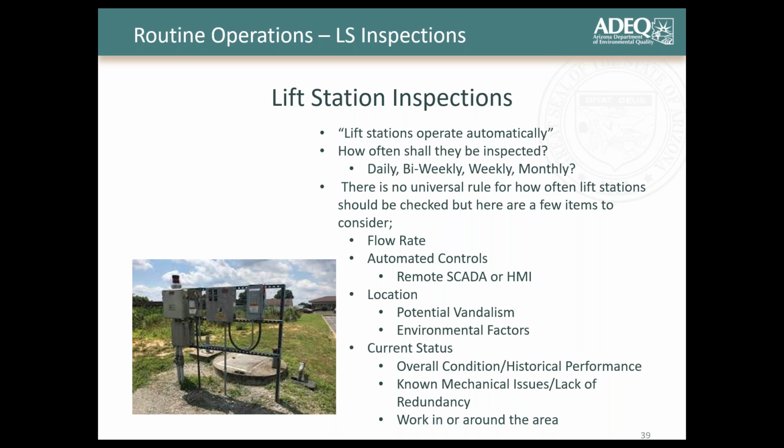Like I said, there were some lift stations that we checked monthly only because they were offline, so we really wanted to check for things like vandalism or other potential environmental factors. And if this is a lift station whose overall condition or historical performance hasn't been really great recently, or has been great, that's going to make a difference in how often you want to be there.